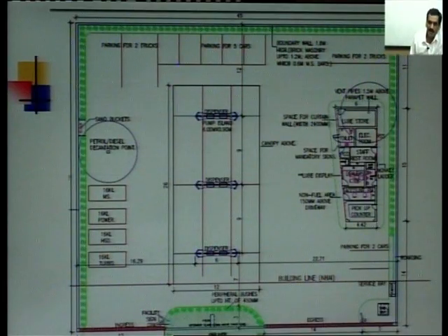So pipeline in a petroleum outlet is a GI pipe. GI stands for galvanized iron. Galvanized iron pipeline, C class. There are 3 types of pipes, A, B and C. This is a classification in our plumbing. So C is the highest rated, the best and the thickest. Those kind of pipes are used for carrying the fuel from these tanks to our dispensers or machines.